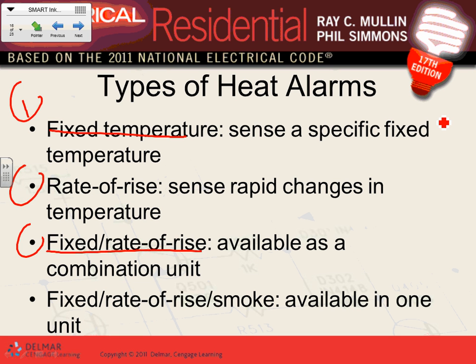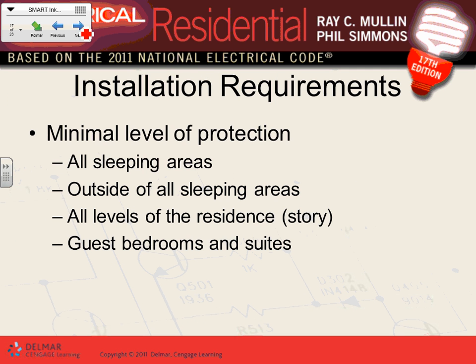Okay, so that's basically it, and better of all, you can have a heat and smoke detector in one combo. Right? It senses smoke, and also senses heat. And it senses fixed heat or rate of rise. Can I have thumbs up, Chad? Rate of rise and smoke. Okay, so these are the technologies they have.